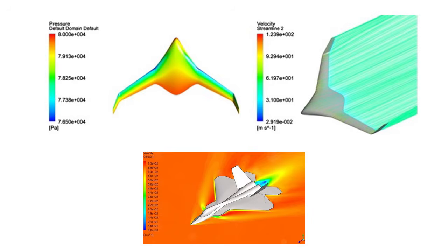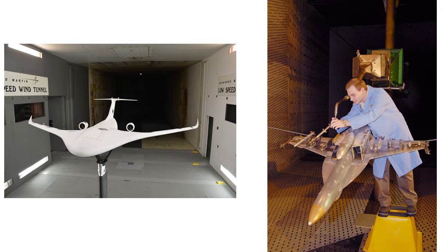Naturally, the next step to bridge the gap between theoretical analysis and real-world performance is a proper CFD analysis and aircraft study. I might make another high-level video outlining things like CFD turbulence models, flight envelope simulation, steady and unsteady analysis, and how to interpret the results, because there are hours and hours and hours of details to discuss on each of those. The last approach to verifying stability characteristics and estimating the derivatives and coefficients is low-speed wind tunnel